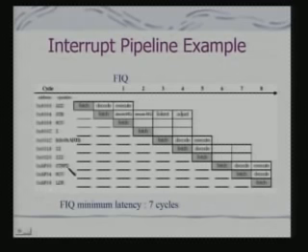I may do something else as well, but at this vector I have a branch instruction. This branch has to be executed to actually move into the interrupt handler, and so there is a delay of about 7 cycles, and this is how the pipeline would behave. Once the interrupt occurs at this point, adjustments take place corresponding to the interrupt.